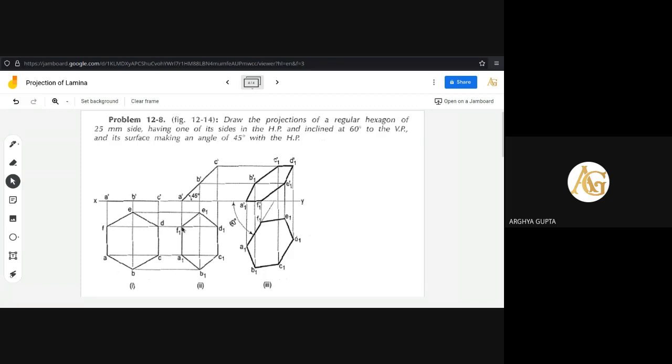So now take the measurement here. Just follow my cursor from this to this. Okay, so mark a point here. Now through that point, draw a perpendicular line. Draw a perpendicular line again, and take the measurement from this point to this point and mark the point here. So hence you will find E1.